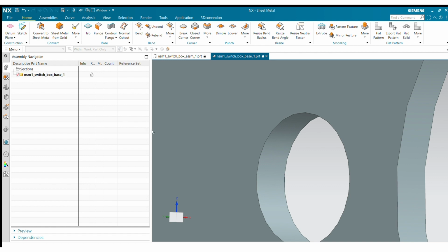So depending whether you want this resolution at a fixed level, part level, or view level, you can go ahead and toggle those. So in this case, we'll stick with part since that's the default, and we'll increase this to extra fine. We'll hit apply, and you'll see those changes display here.